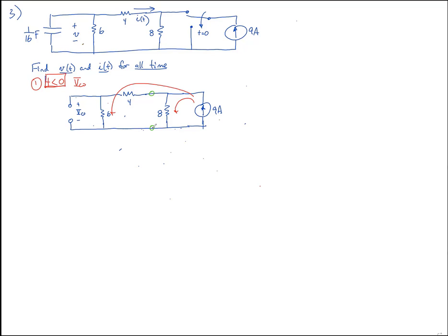Wait a second, aren't these resistors in series? Aren't there some resistors in series here? Yes, because there isn't any current flowing through the VC naught. So you could say because there's no current flowing through here, all the current flowing through this 4 ohm is flowing through this 6 ohm too. Hey, take a look. We could even draw it like this, right? And now there's only these 2 wires that are coming out of my node. So therefore that proves that it's in series, right? Yep, these are in series. Why can't we do this? Why is that a mistake? Why will that screw you up?